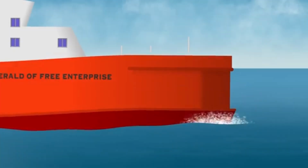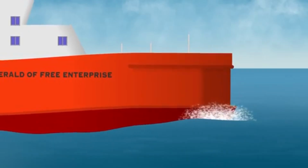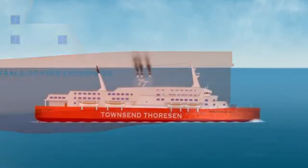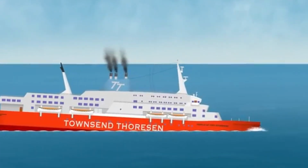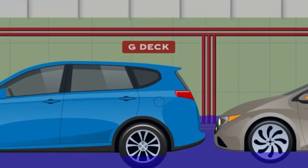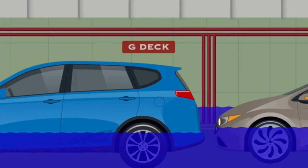The remaining ballast, combined with the squat effect from increasing speed, and the bow wave, again from the increased speed, meant that the water level ended up above the bottom of the open bow door. Within seconds, Herald of Free Enterprise was scooping up tons of water, lowering the bow even further and completely destroying her stability. The open nature of the vehicle decks on these sort of ferries quickly leads to a loss of stability in a flooding scenario thanks to a thing called the free surface effect.